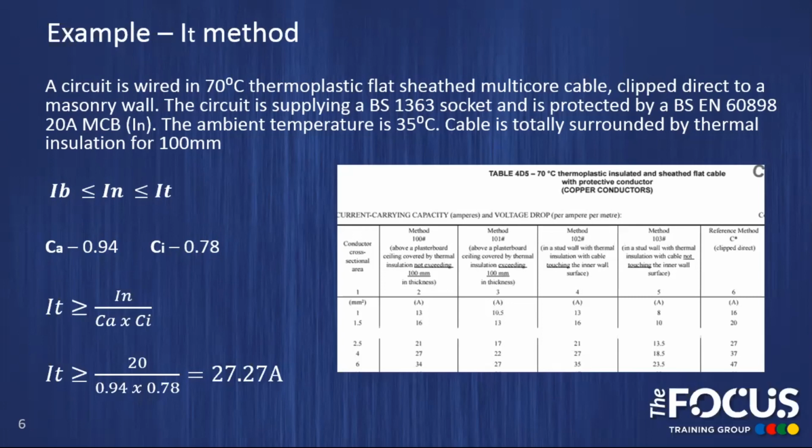We can see now that, as described in Appendix 4 of BS 7671, using this method may be slightly preferable to using the Iz method. And it is key to remember that using this method, it is not necessary to really know the value of Iz.